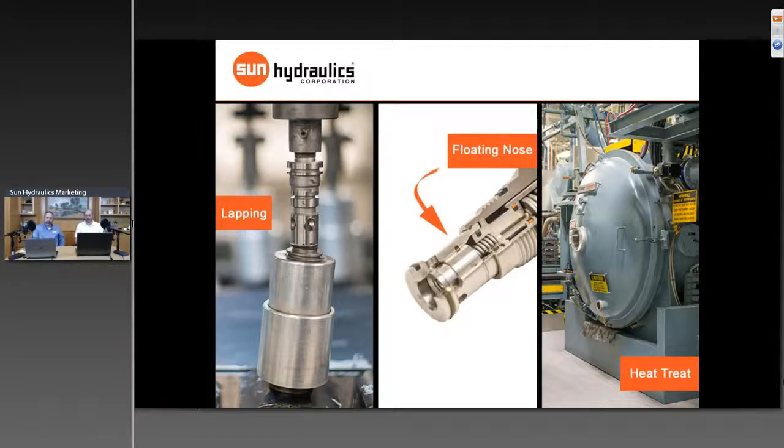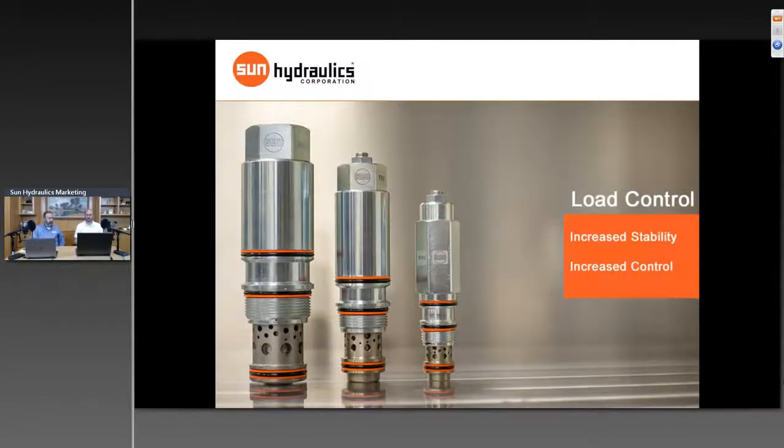This was a completely different construction than the standard counterbalance valves, specifically designed to be more stable through better modulation, and more applicable to a broader range of application circumstances. So we've taken our knowledge of a good product and tried to come up with an even more clever, more robust counterbalance that could be applied to a wider set of circumstances.